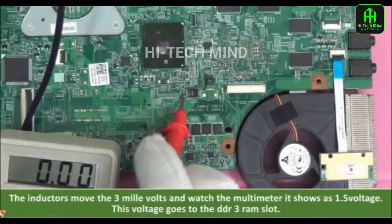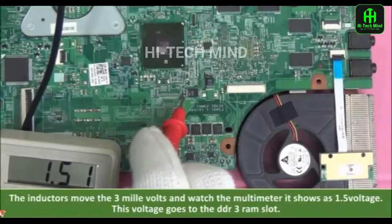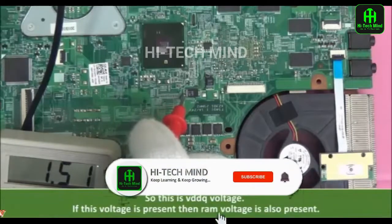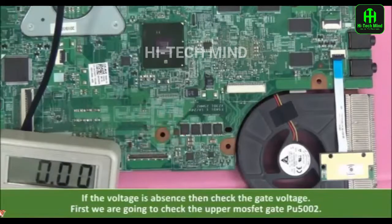The inductor output, watch the multimeter. It shows 1.5 voltage. This voltage goes to the DDR3 RAM slot. So this is the VDDQ voltage. If this voltage is present, then the RAM voltage is also present. If the voltage is absent, then check the gate voltage.